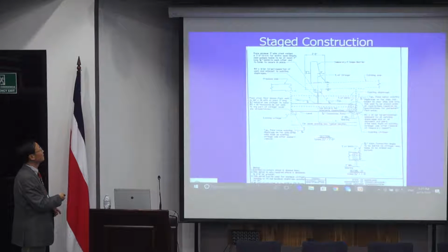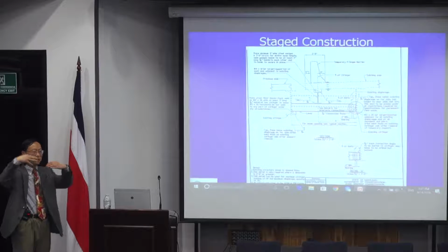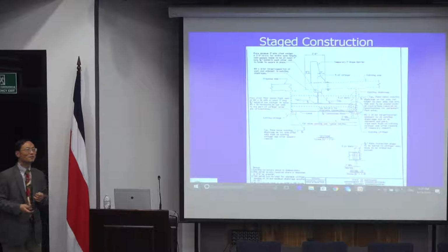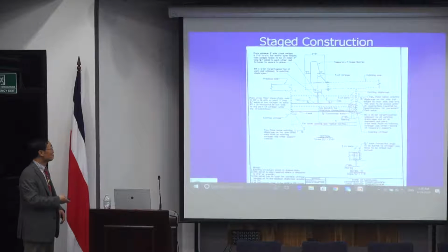So you put a stringer, then you just put a wedge. Typically you can use either timber or steel. Timber is fine. You just have two wedges, tie them together every meter or so. Then you grout continuously, so that after doing that, the slab is continuously supported by these stringers. Now this slab is no longer a cantilever. Not only that, when the truck load comes here, all these girders will be sharing the load just like before. So that solved both problems.